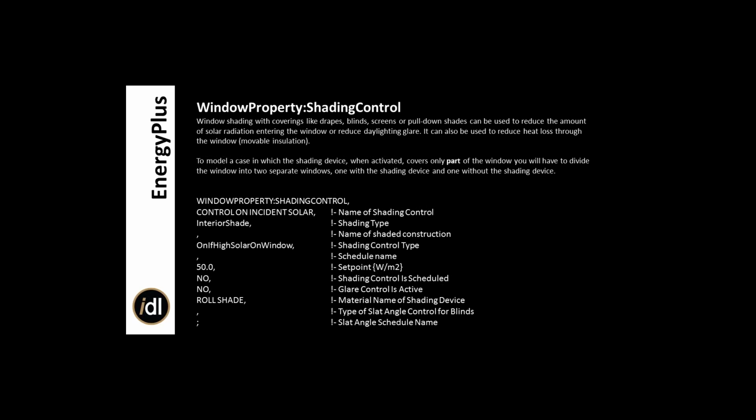So on the next step, we need window property shading control. Window shading with coverings like blinds, screens, pull-down shades can be used to reduce the amount of solar radiation entering the window or reduce daylighting glare. Also, if we want to model a case in which the shading device covers only part of the window, you will have to divide the window into two separate windows, one with shading device and one without it. And you have to put that in EnergyPlus.